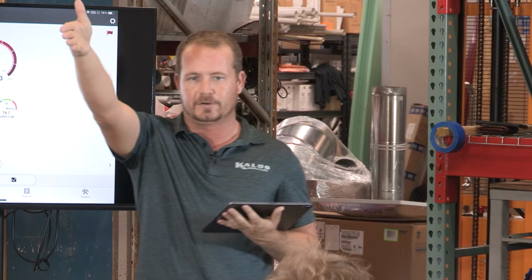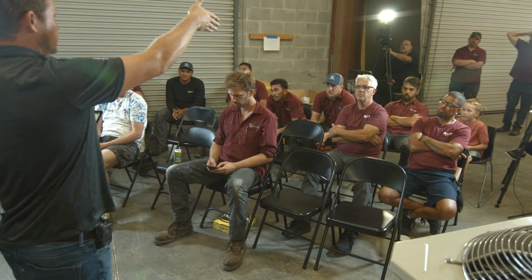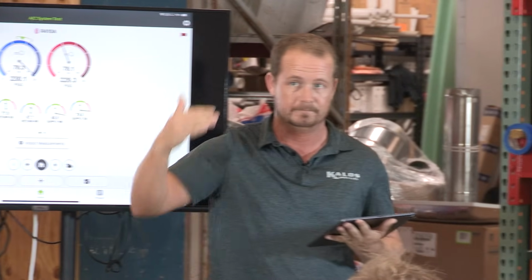The heat transfer is less. You'd have much less heat transfer, right? Why would you have much less heat transfer? You have less surface area, you have less turbulence. So there's less time and turbulence. There's less dwell time. Those molecules have less contact time, right? So they just rush right past. They're not sitting there and contacting those fins, which then contact the tubing, right?